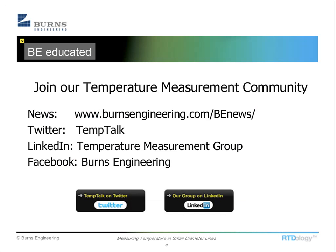From a question perspective, we have a question as to what do you recommend for heat transfer medium for sanitary applications? Ooh, there's a good one. We use a zinc oxide silicon oil paste, which is very similar to what is used to heat sink IC chips on circuit boards, and that works fairly well.